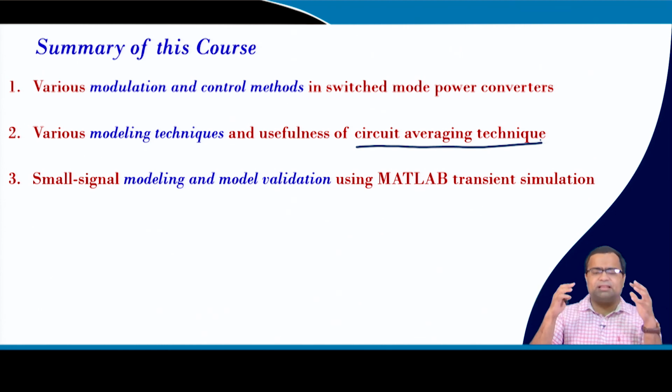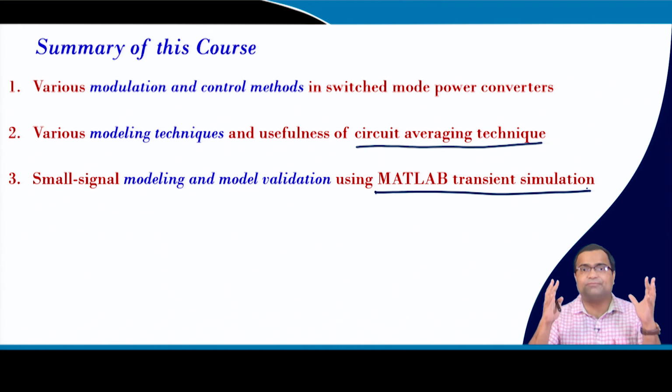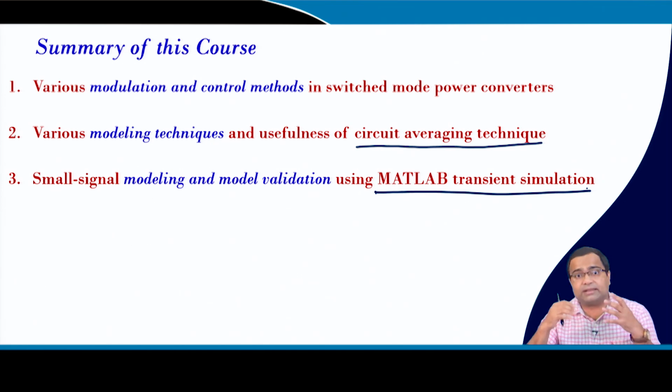Then we introduced small signal modeling as well as derived small signal transfer functions. We validated those transfer functions using MATLAB transient simulation, and this is one of the very important features, because you want to understand whether the models are really valid, whether your design using the linear model, by closed loop simulation, is going to match the actual switch simulation.